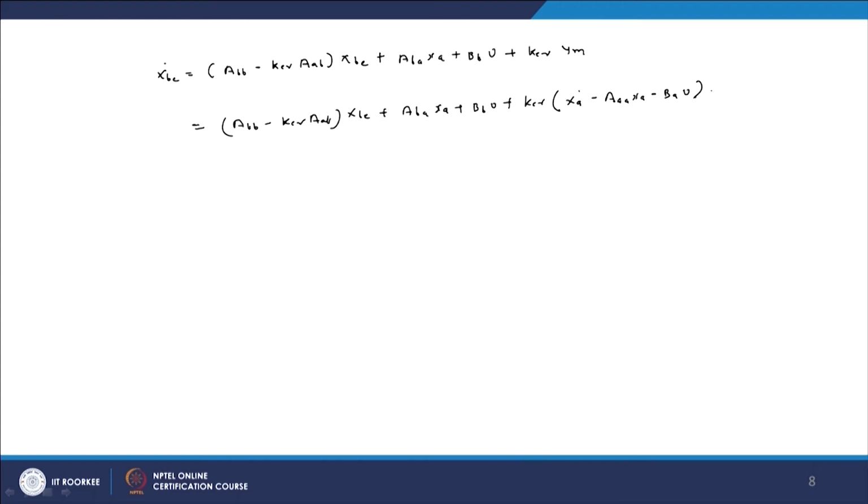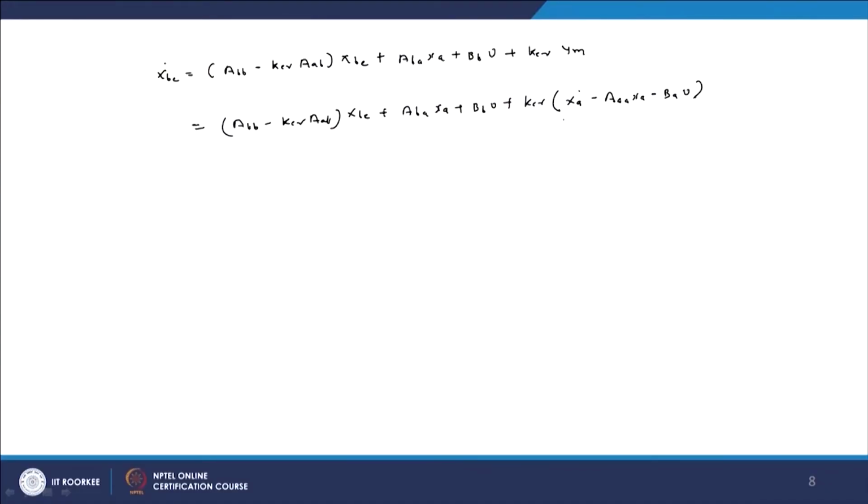So, now these equations we have solved. Now, we have to see the point. Here we have got the state equation for the minimum order observer XB dot, but now here XA dot is there. Since y equals XA, and in the state equation we get XA dot, that means noise is there, it will amplify and that creates problems. Therefore, we have to remove the effect of XA dot, that means in the equation there should not be terms like XA dot. So, in order to handle this, we write the above equation as